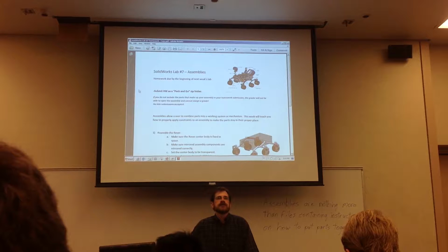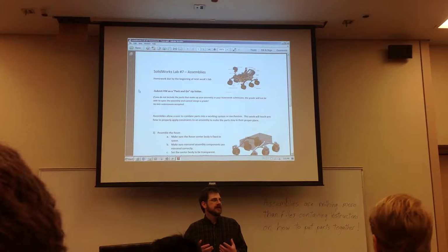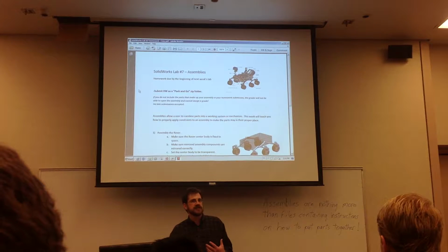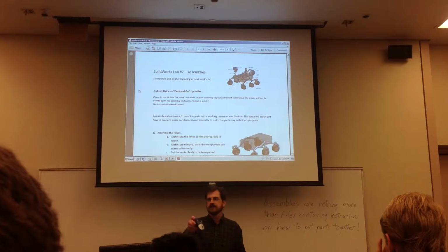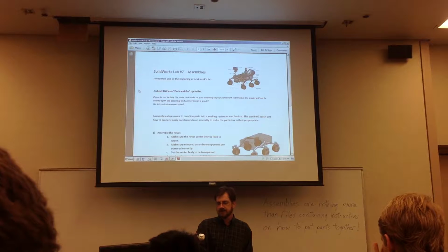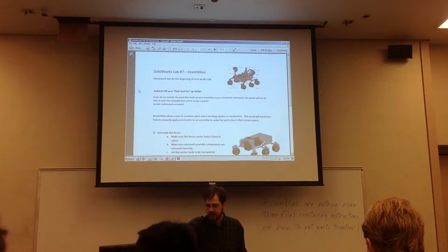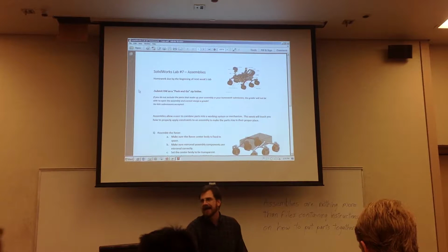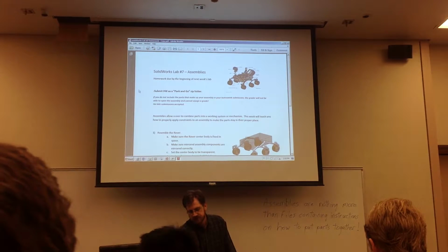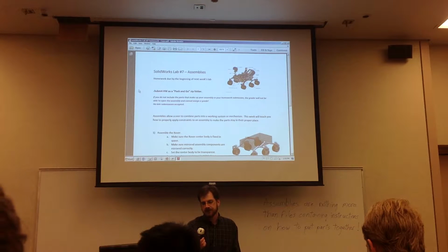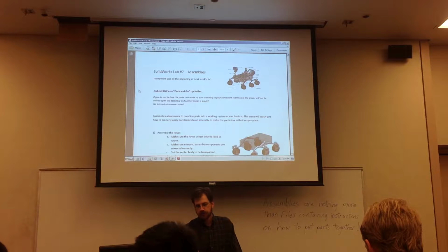Now, the Sketch Picture tool allows you to take a photograph or any other image file and actually import that image into a SolidWorks sketch so that you could just trace over it. For example, if you were going to create a SolidWorks model of something like this mouse, some oddly shaped object, it would probably be easiest to just take photographs of this mouse from above, from the sides, from the front and the back, bring those photographs in on different sketch planes, and then just sketch some splines over the edges of the picture and produce a wireframe model that then you could use surfacing to produce the SolidWorks model.